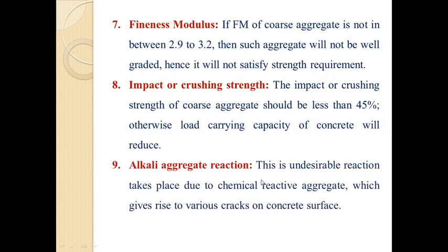Next is the alkali aggregate reaction. This is an undesirable reaction that takes place due to chemically reactive aggregates, which gives rise to various cracks on the concrete surface. So aggregate should be selected in such a way that it is chemically inert, not chemically reactive. If it is reactive, it will react with the alkali and give various cracks on the concrete surface. So we have to take care that the aggregate should not be a reactive one.